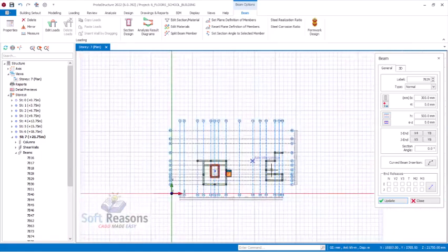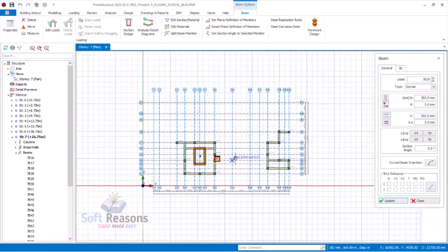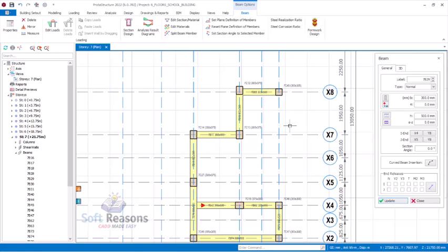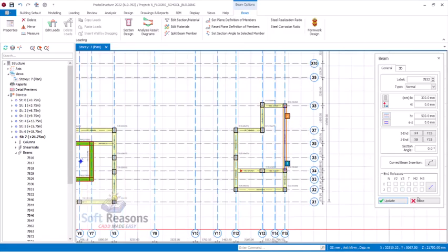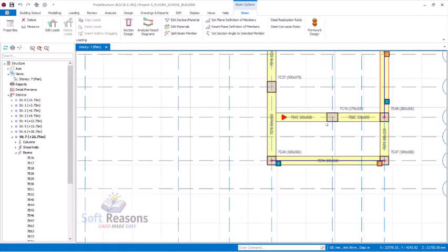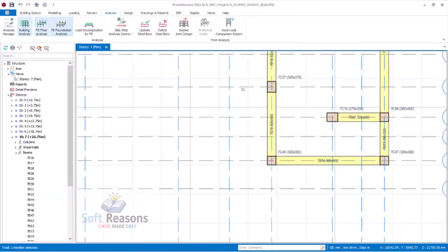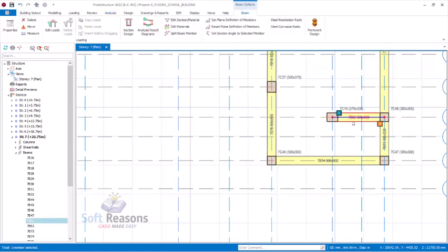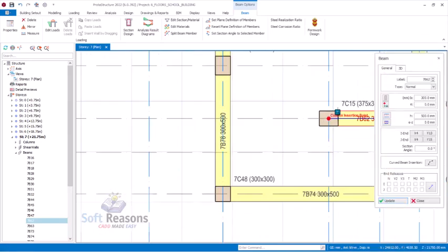Alright, so now we see this is the topmost seventh floor. Okay, so we will close the stair room. Have that provision closed, after which we will be applying wall load on this. This is not supposed to be a cantilever, because the end is not free. So we will make it a normal beam by using the property of that one. Place it just like this.